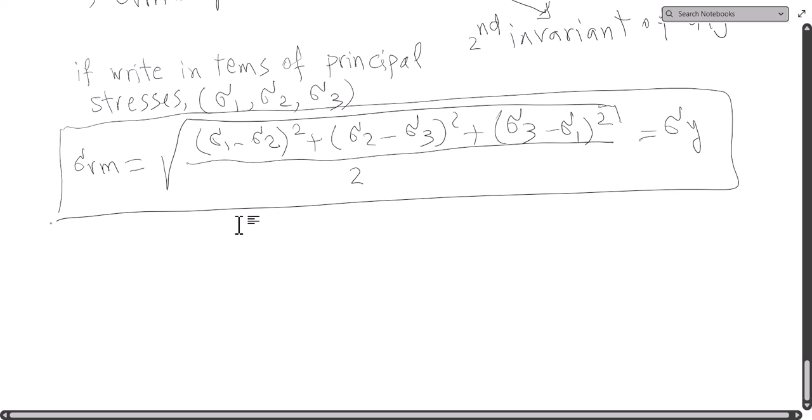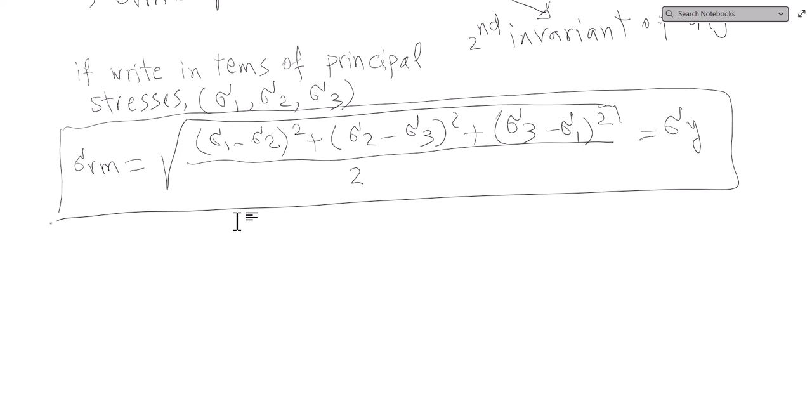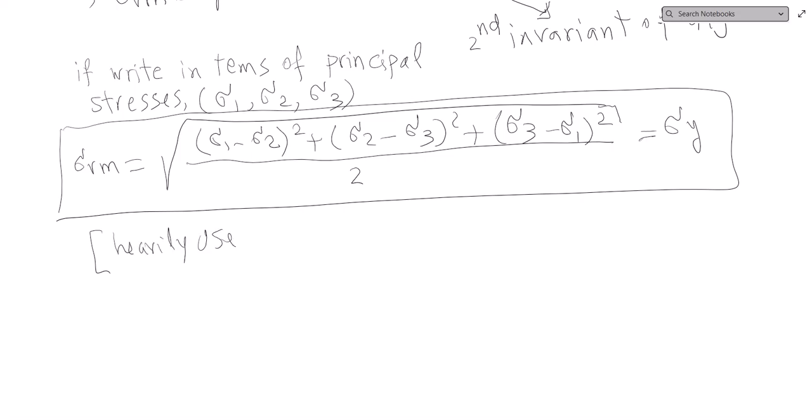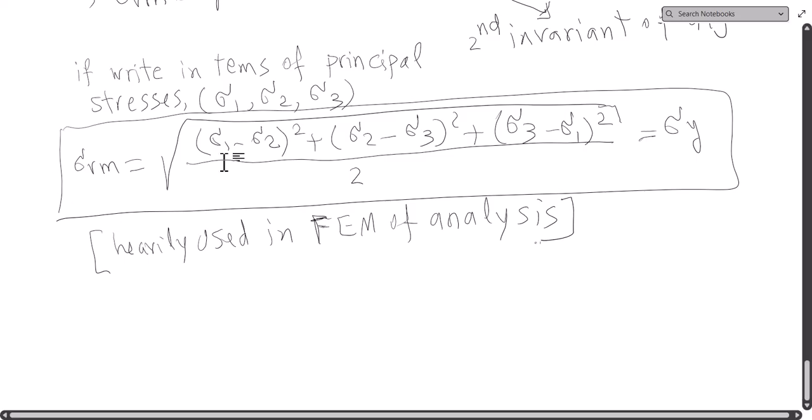When we have the state of stress, and this is heavily used in the finite element method of analysis, we get our principal stresses, calculate this relationship, and this should be not more than sigma y.